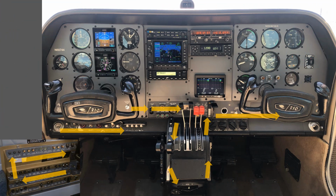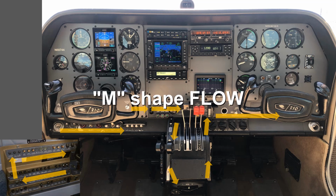So I start over in the lower left on the circuit breaker panel and then come across on the switch panel, which is to the left of the pilot's knee. Then I come along the bottom of the panel, check that all the switches are off, then come up and check the gear is down, go down, check all the trims and the fuel down below in the middle that you can't see, and then come back up and go over toward the right side of the panel. So let's look at this actually in the airplane.